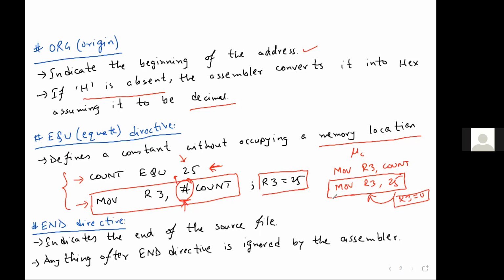The microcontroller, when you write this line in a cleared memory, will go to this address. So the memory is cleared, so address 25 memory will also be cleared. So in that particular address, the content will be 0. So that 0 will be moved to R3. Have you got my point? Yes, sir. Okay. Any other question?